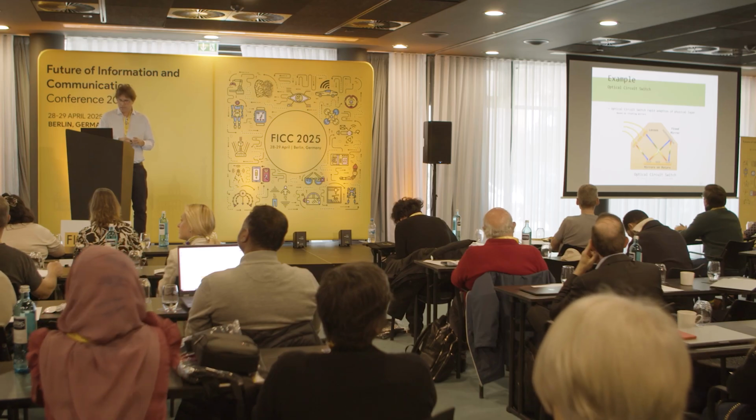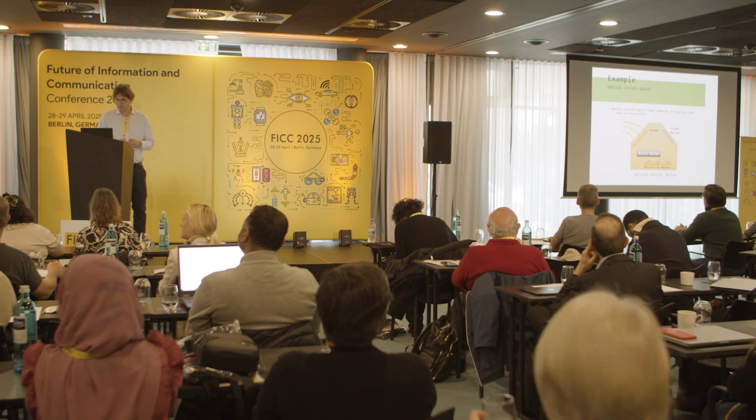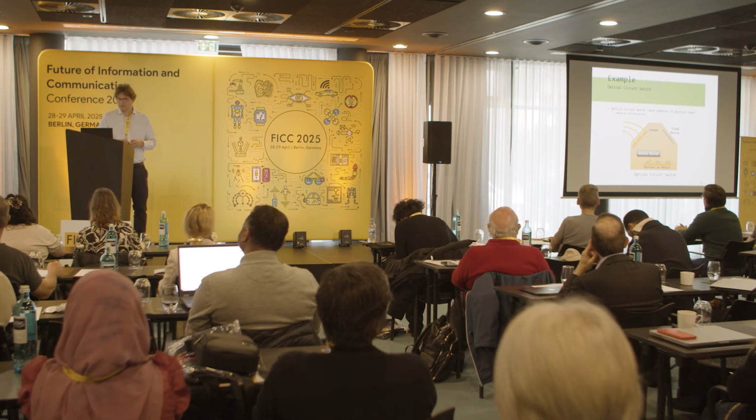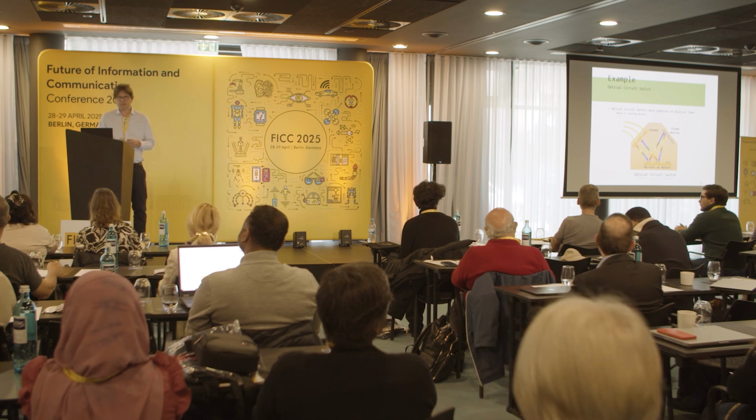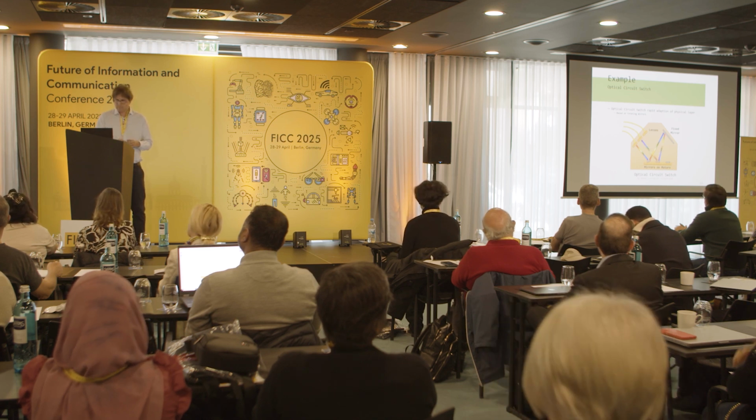Now if this router has movable mirrors, or mirrors that you can program, then you could change the angle of this mirror, for example, like that. And now if the light enters here, it will be reflected differently, and it will actually go out through the middle port. So you can dynamically change the interconnect by changing these mirrors.